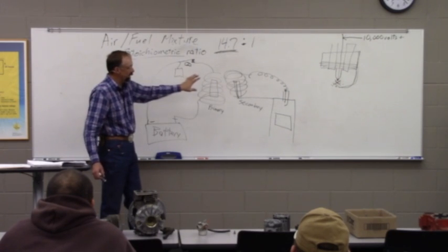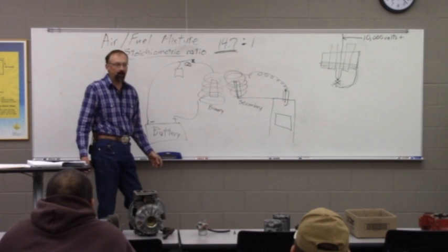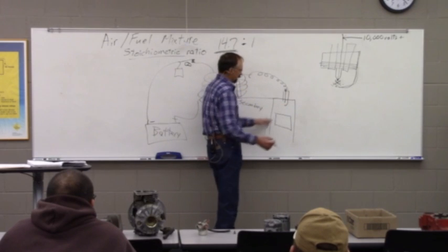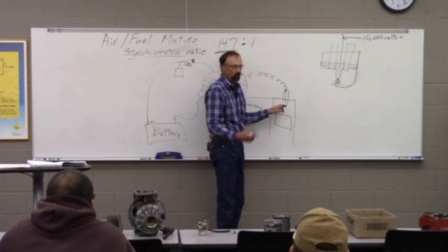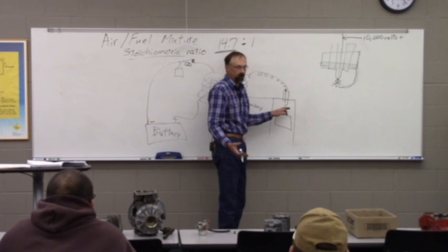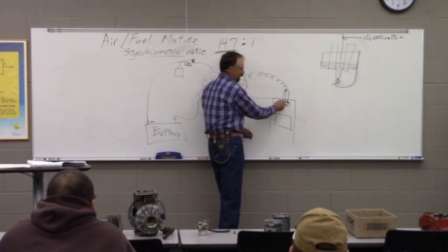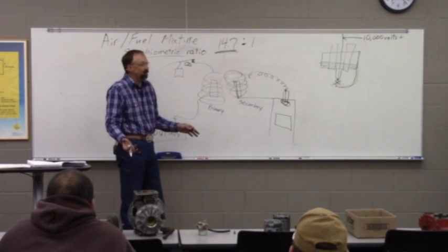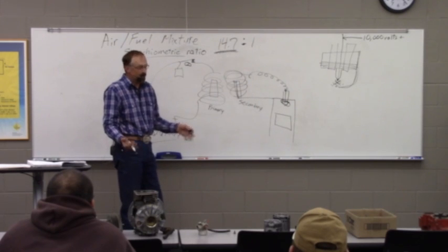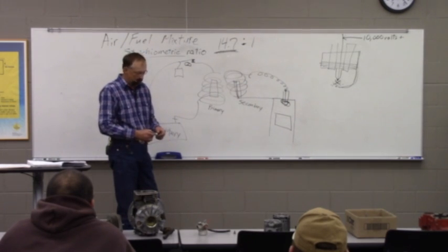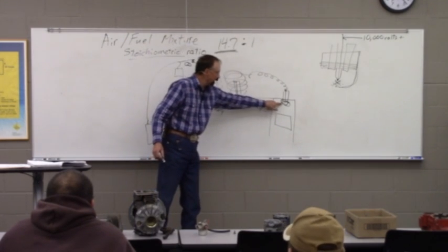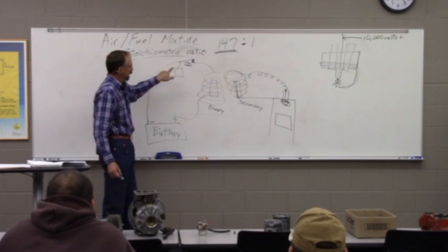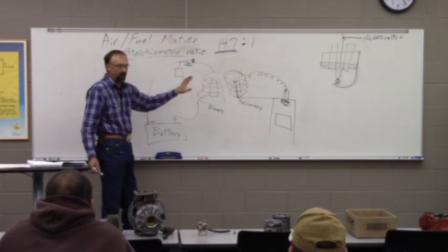And likewise, because of the inaccuracy of the carburetor, you'd typically have enough carbon buildup, and some because of the excessive heat whenever the engine was lean, the spark plug would be trashed. So we were looking typically every 10, if everything was really good, maybe 15,000 miles, you were looking to take your vehicle in for a tune-up. And a tune-up primarily included replacing these spark plugs, replacing these points, replacing this condenser, and making some adjustments to all that and your carburetor.